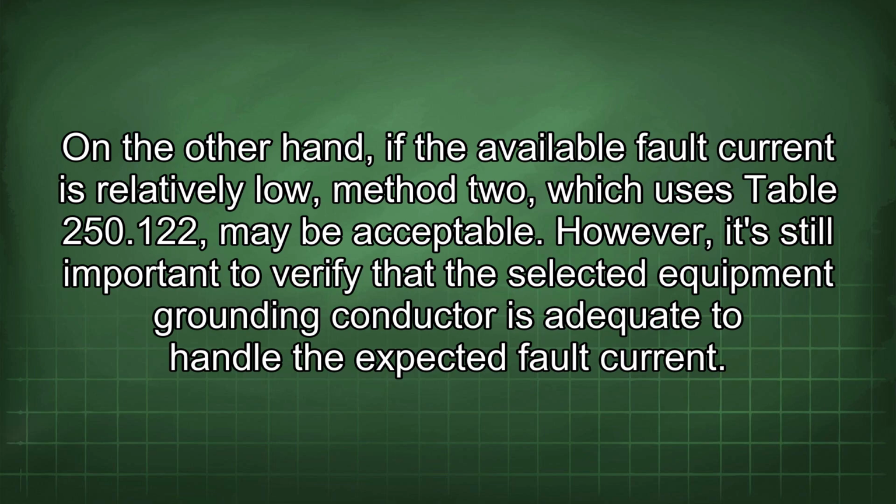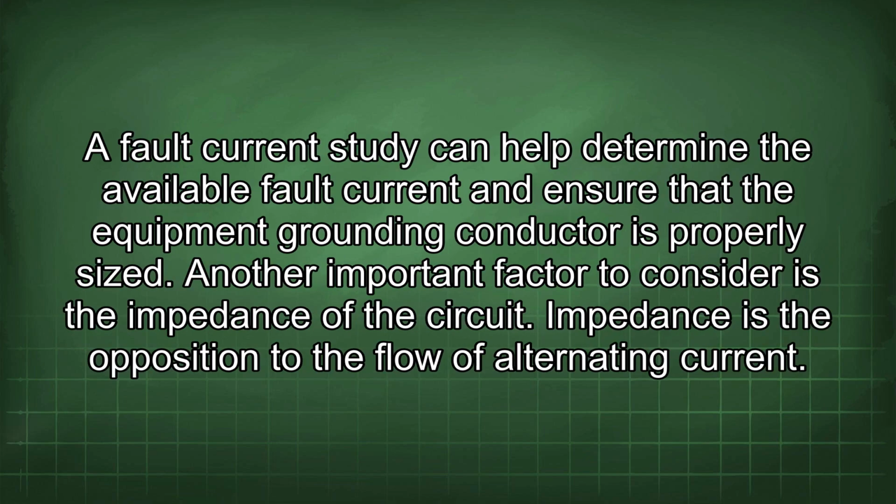Table 250.122, may be acceptable. However, it's still important to verify that the selected equipment grounding conductor is adequate to handle the expected fault current. A fault current study can help determine the available fault current and ensure that the equipment grounding conductor is properly sized.